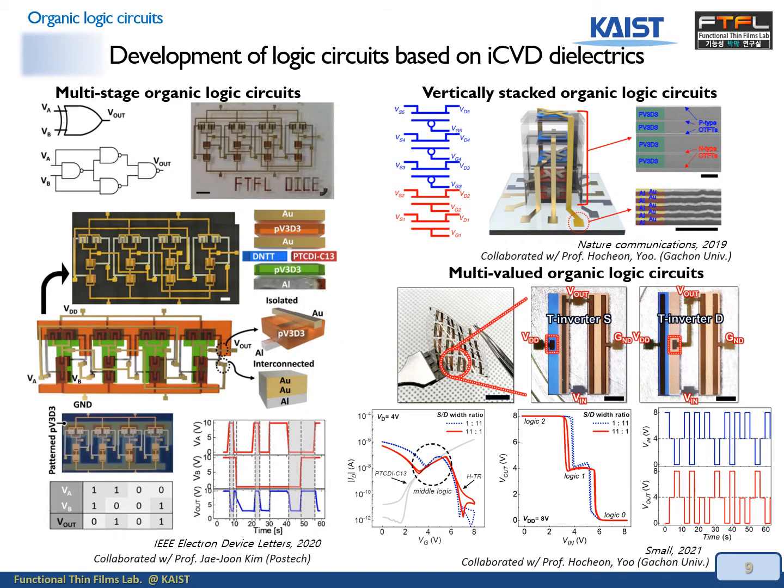First, insulating films are used to design logic circuits. Through thickness control and patterning, multi-stage logic circuits with various structures and electrical characteristics have been realized. Recently, a flexible ternary circuit with low power operation has been demonstrated through the iCVD process.